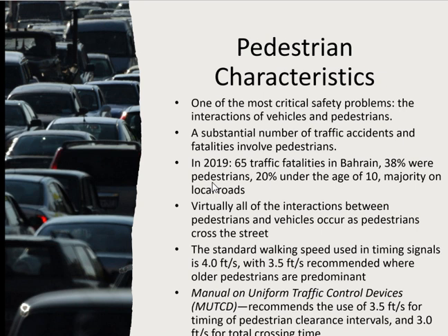Some values are given here if you want to design a pedestrian signal, and we used them at the end of the last chapter as well. These are the same values for checking the timing of the signal. If you want to design a pedestrian signal or check the timing of a signal at an intersection, you need the pedestrian speed, how fast they will cross, and using the width of the road, you can calculate the time.